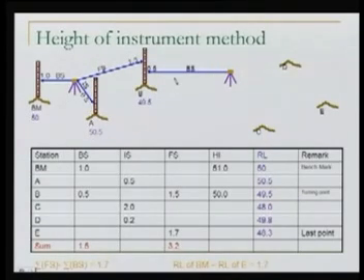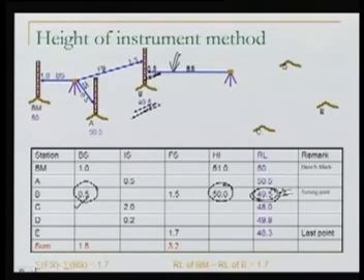Well, once we have taken the back sight, we know now the height of the instrument. Height of the instrument is RL plus the value here. So our next height of the instrument will be computed because in our table here, we'll write this back sight on B. Okay, please mind it, the back sight on B, and once we have done it, we know the RL of B also. So RL of B plus back sight on B will give me the height of the instrument. So we know the height of the instrument now here.